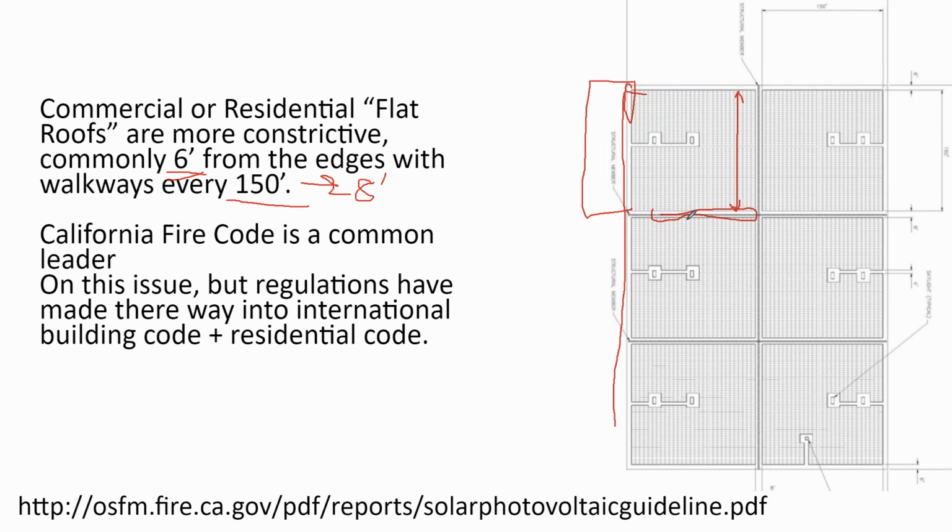Yeah, I was doing a commercial project, and the array was supposed to start exactly 6 feet from the edge of the roof. And per OSHA and the prime contractor's OSHA inspector, he says you need to set up your perimeter with your flags, and if you're outside that perimeter working 6 feet from the edge, you need to have your full protection on. You know what? It would have saved us a whole lot if we could have started the array 8 feet from the edge of the roof instead of 6.